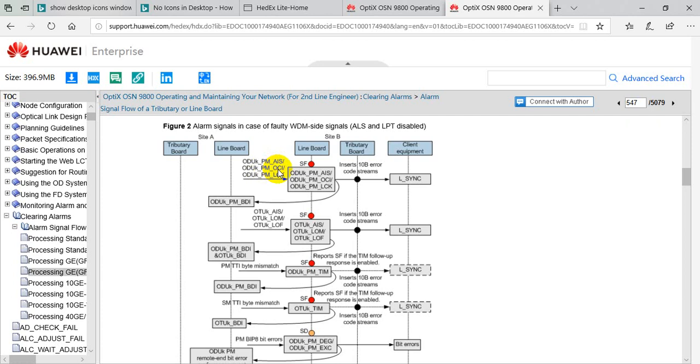In terms of OCI, open connection indication, if it is received at B at this line board, it means some connection in the trail is missing at site A. So OCI is also signal failure, and if you take some trail under maintenance, then also there will be a problem, because that will be tested by an internal tester, or it will be forcibly deactivated or something, then you will have this type of lock alarm, which is also showing the non-availability of the services. So that is also categorized as signal failure.